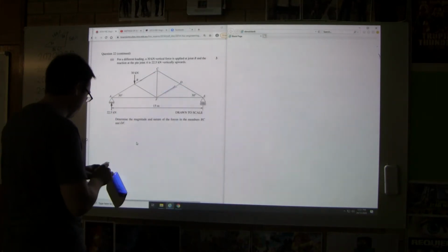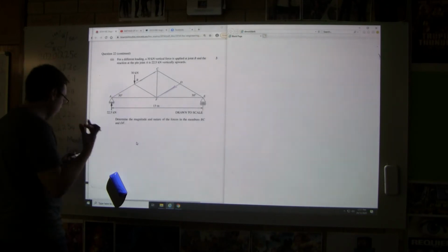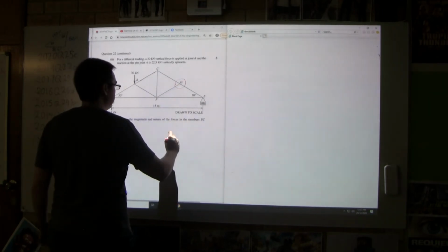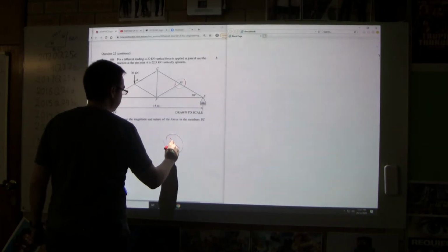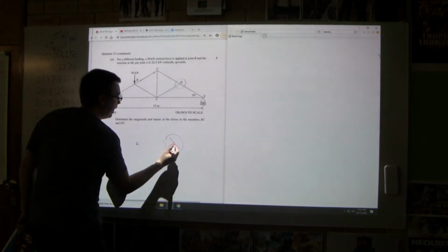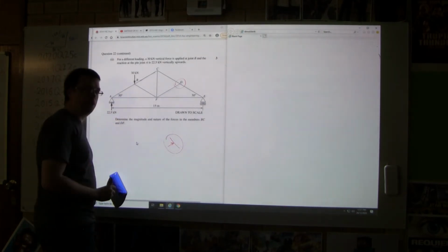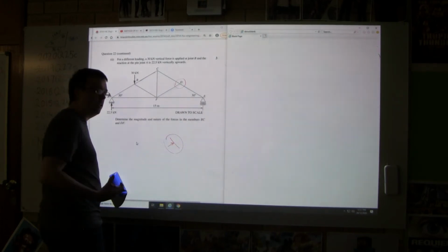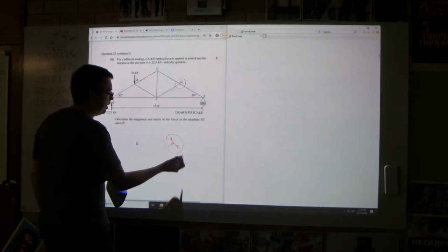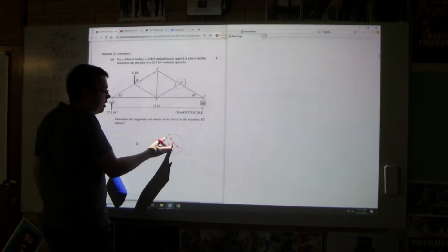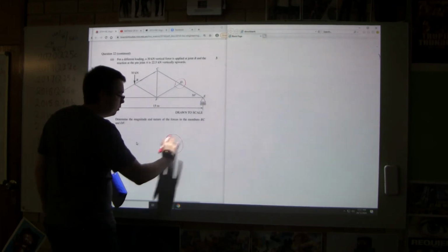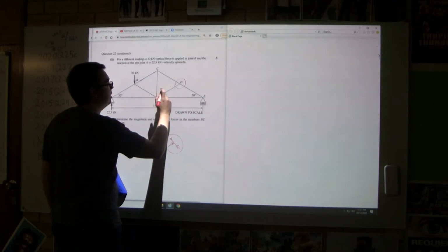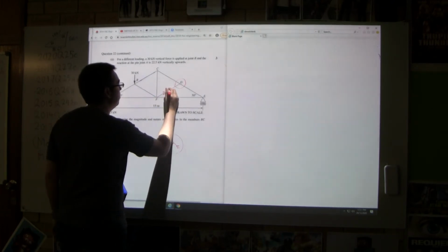Okay, so how are we going to do this? Well, I'll start with DF. If I inspect this joint, if this has any amount of pushing to the right, there's nothing here that can push enough to the left. This and this have to balance each other, so this can't provide additional right, this can't provide additional left to balance that in any amount of right. So that means that this has to be a zero force member.